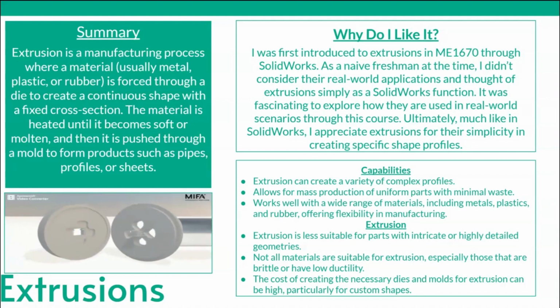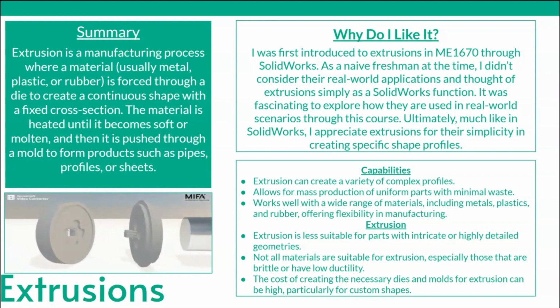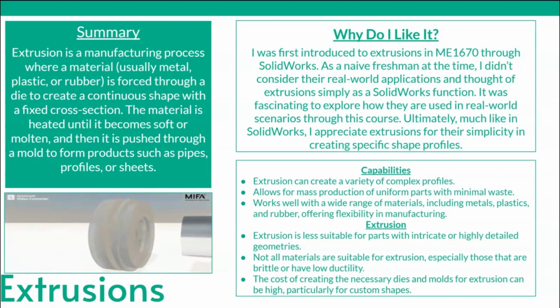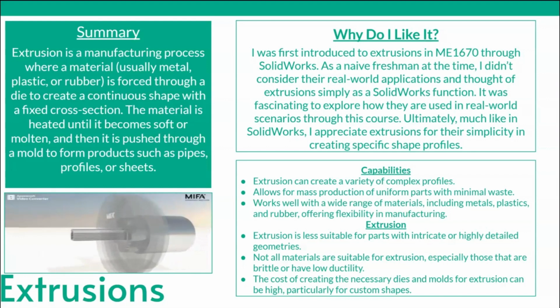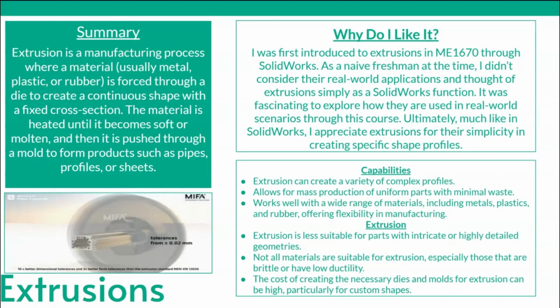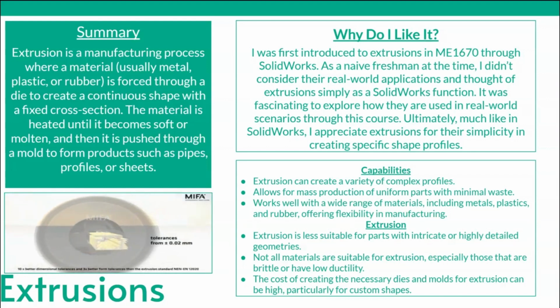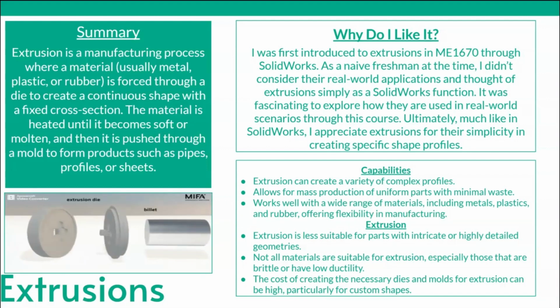So some capabilities of extrusions: they allow for a variety of complex profiles. They allow for mass production of uniform parts with minimal waste. This should say limits, but extrusions are less suitable for parts with intricate or highly detailed geometries. Not all materials are suitable for extrusions, and the cost for necessary dies and molds could be high.